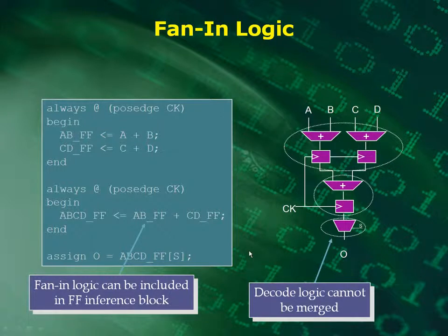Any questions at this point? How come I didn't stick this back behind this flip-flop? That's my question for you. Could I have done that? Yes, you could put it back here if it didn't make a difference in timing. It could be that when this clocks at this flip-flop here, S isn't at the value that you want yet. So it may be a timing thing where S is not valid until this clock edge, and so you can't make this decision until then.